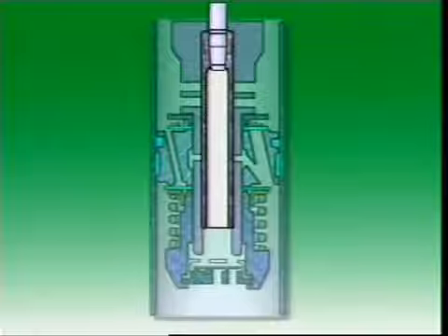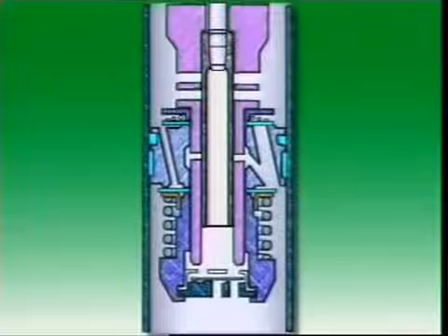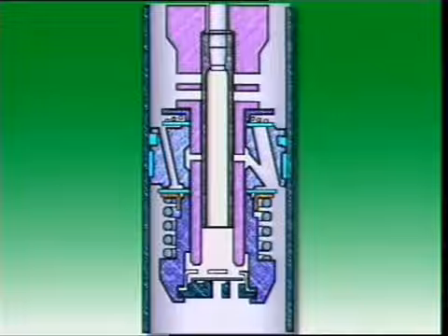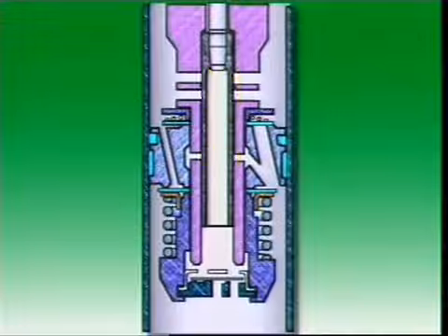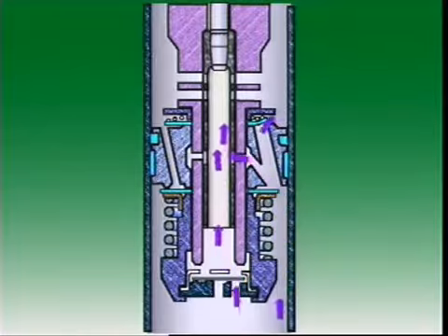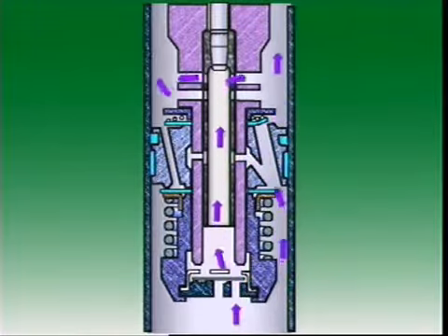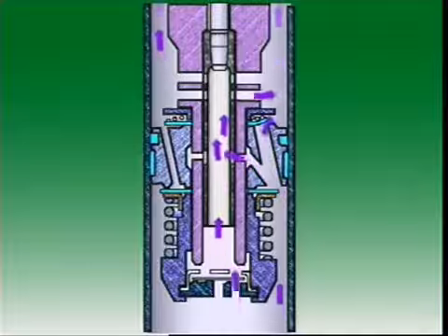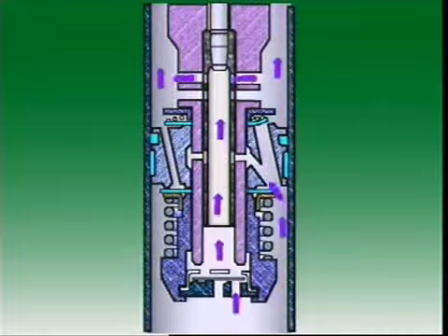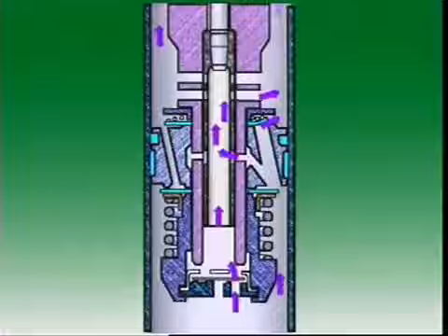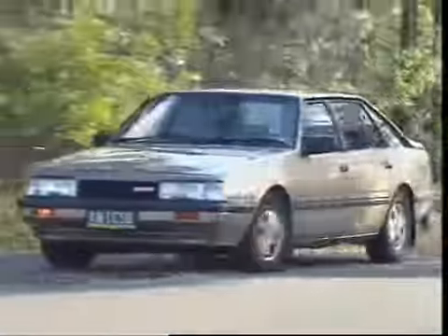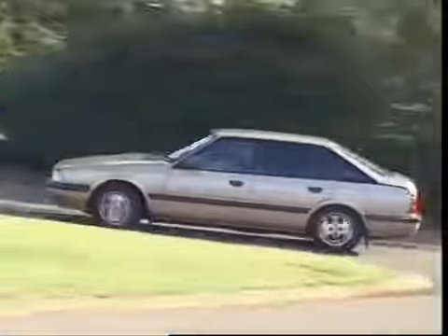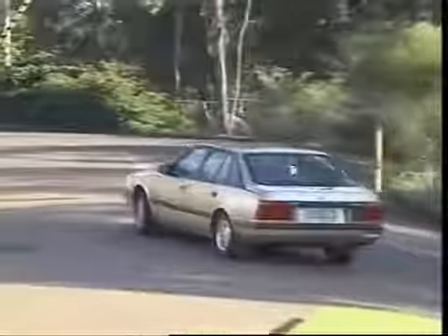Each shock absorber has a rotary solenoid that can alter the dampening rate by changing the number of restrictions the oil must pass through. In this position, all orifices are open. Oil can flow more easily through the passageways in the piston. Only a small dampening effect is applied to the oil. This provides a dampening force that emphasizes ride comfort when traveling at low speeds.